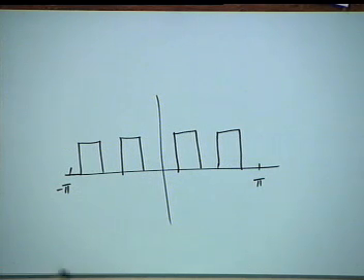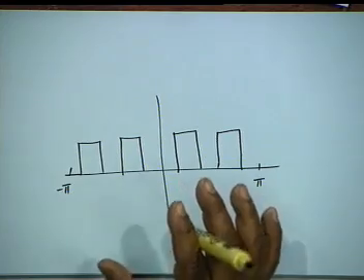Okay. So FIR filter design is not as hopeless as it poses to be. It is a hit in the dark, all right, but anything that works finally is good enough for an engineer. I have shown you what happens when you increase the length to 1023. The filter that we get is almost ideal. We can never get such a response with an IIR filter.